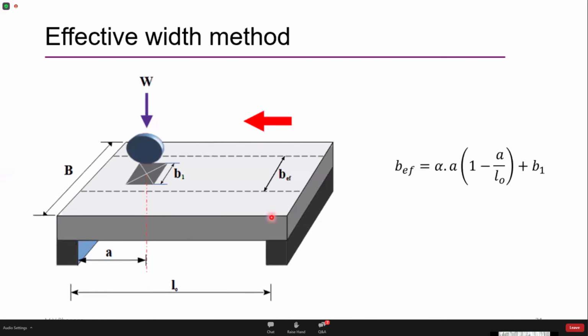So let's try to read this diagram. What I have here is a simple slab, or rather I'll call it a deck slab, of length L0 and width B. This slab is resting on two opposite sides, and these sides we can visualize for the time being as the abutments. Since the slab is supported only on two opposite sides, we are going to have a one-way action. So this slab is going to be analyzed and designed as a one-way slab.